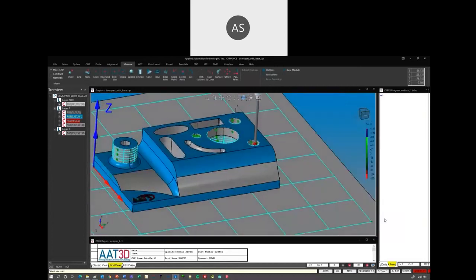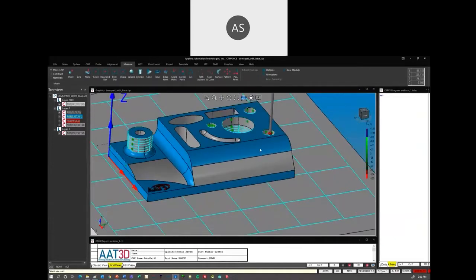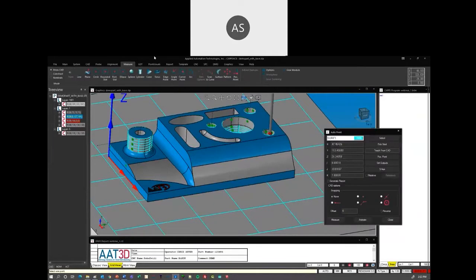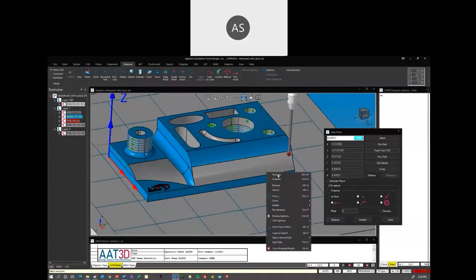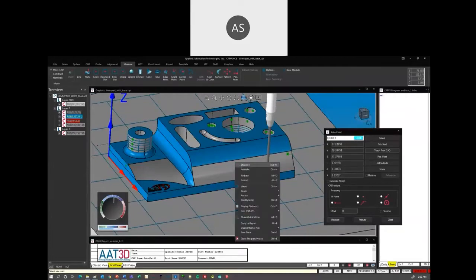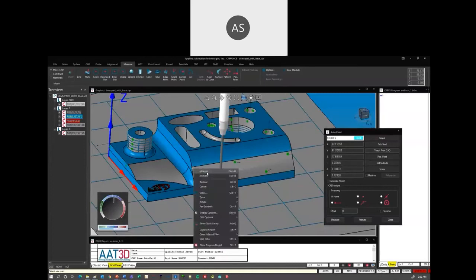Okay. Next, we're going to go down here. We're going to measure some points on this front edge here, and then we're going to do some points on this side edge here. So the front edge here, we're going to just do point by point. So this is a really good tool. If you don't have a lot of points on the surface that you want to measure, you can just click right on the CAD. The software will generate a path, and then we'll invoke what I like to call the lazy man's way of doing this. Click, measure, instead of coming all the way down here to the measure button. So click, right-click, measure, click, right-click, measure, and I can go all around the surface just like that and measure the points that I want.